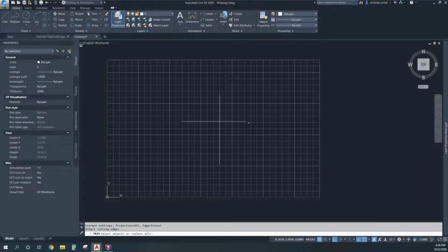The other way, let's say if we wanted to make that same trim, you could select all of the objects this way that you would like to trim and trim it. Or the last way, the most efficient way, is if you know that you want to trim off this section that's highlighted here, then you just select this line because you know that's going to be your trimming line. And there you go, you trim it.